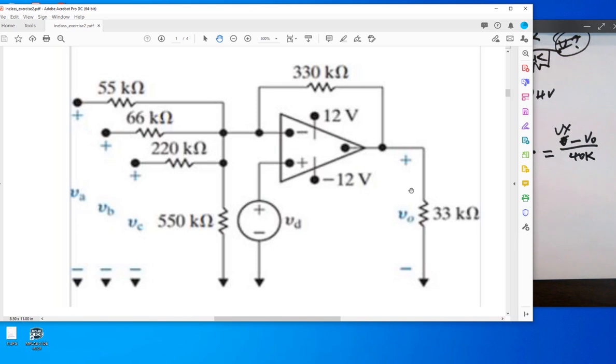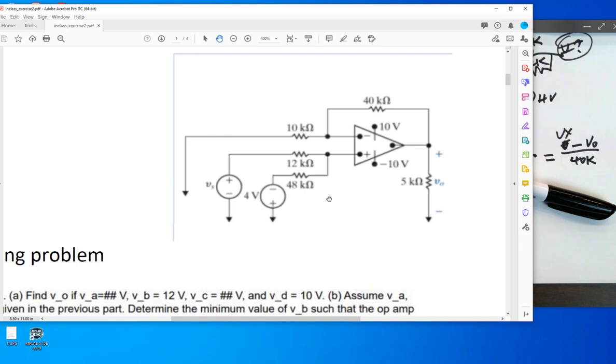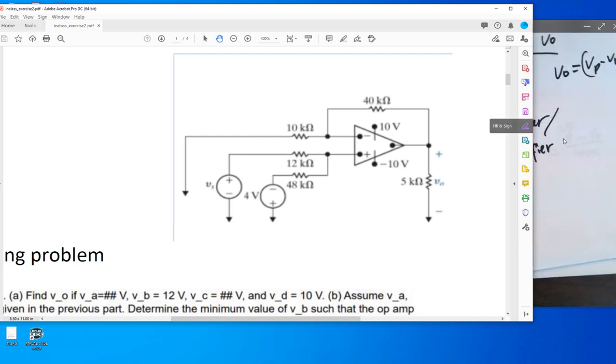Let's say just a summing amplifier, okay? A summing, and eventually it's doing a differential as well. Actually, it's not a really legit question. Even though we don't have a source here, it's 0 volts, right? It's actually using this voltage minus 0. It's still a differential amplifier. The only thing is we don't use it as the traditional differential amplifier like this.